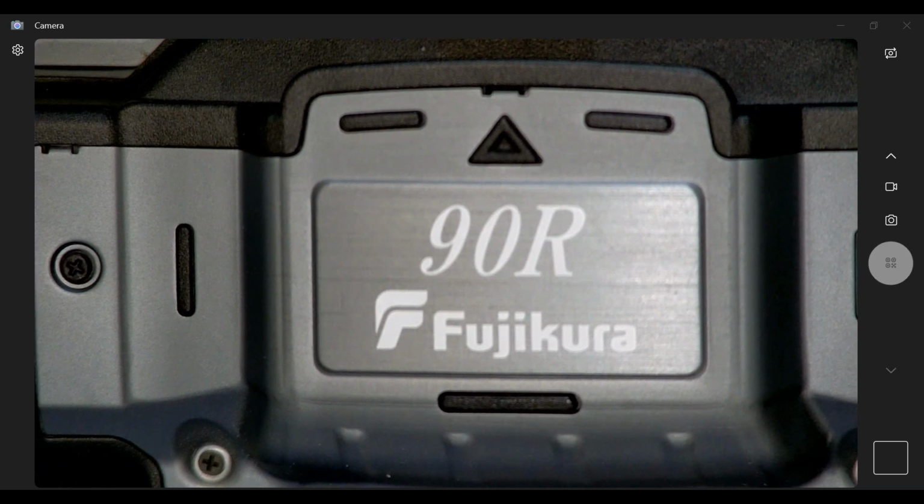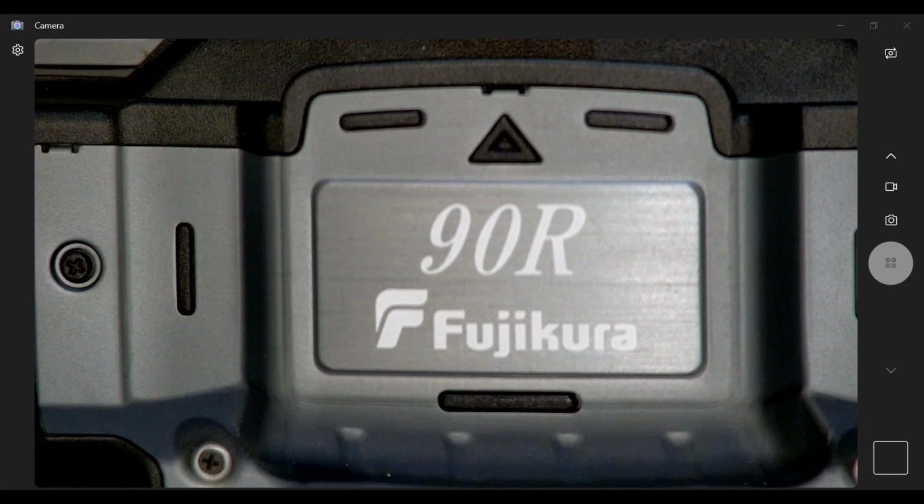Is there any necessary setting when splicing a 200 to 250 micron fiber? So to start off, I would ask you, a 200 250, do you mean a 200 pitch 250 coating diameter, or a 200 200 or a 250 250? That is a very important nomenclature you have to keep adding up whenever you introduce a fiber.